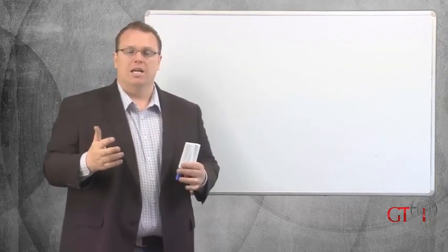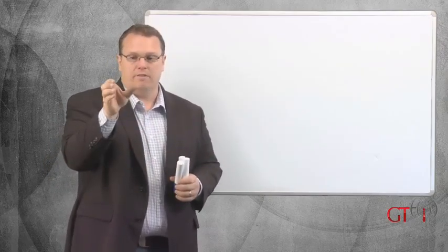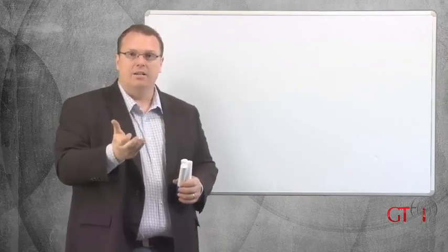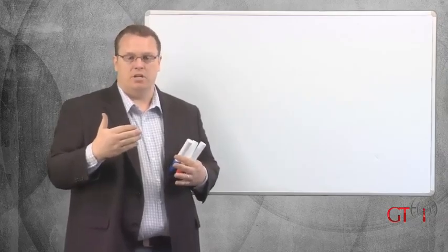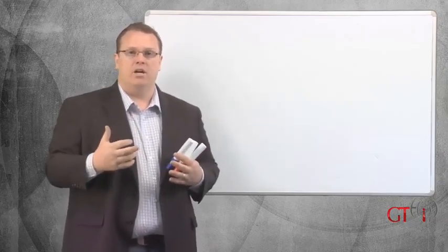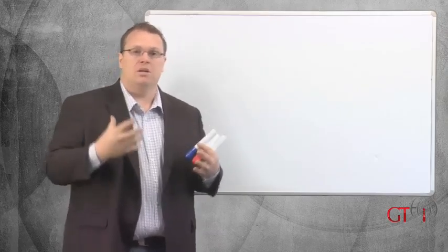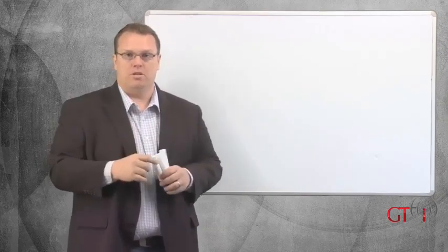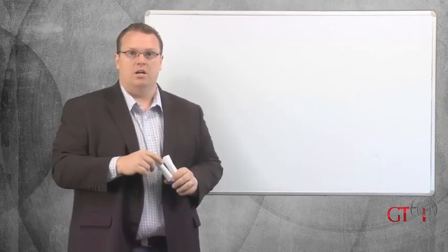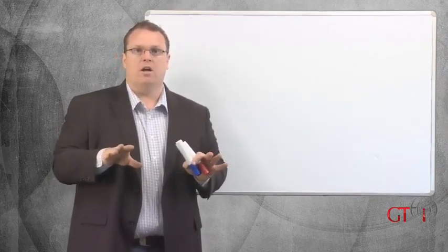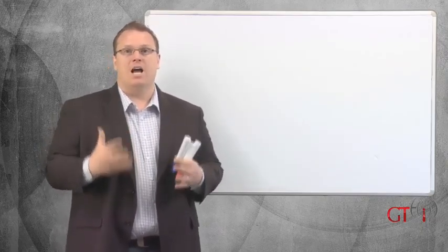That's pretty good. But now we have these mobile devices. People are using them in crazy ways, like vertical and horizontal and even flat. Now you're changing the polarization relationship between the transmitter and receiver. So the best systems out there actually are dual polarized. They have access points that can actually transmit and receive in multiple polarizations. It's not as easy to do as it sounds, but it is very important to do that. So hopefully that's a good understanding of polarization. Now let's get into the different antenna types.